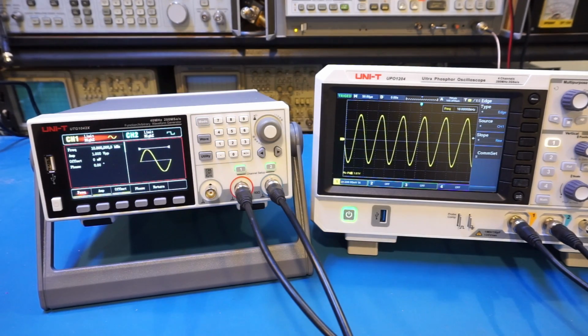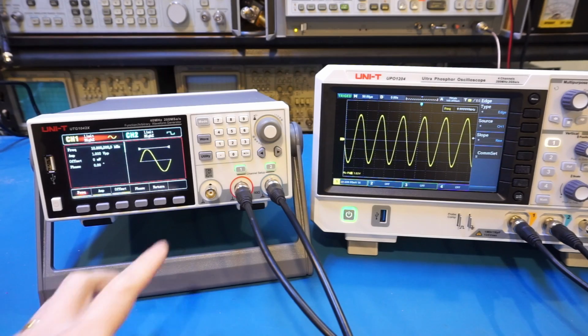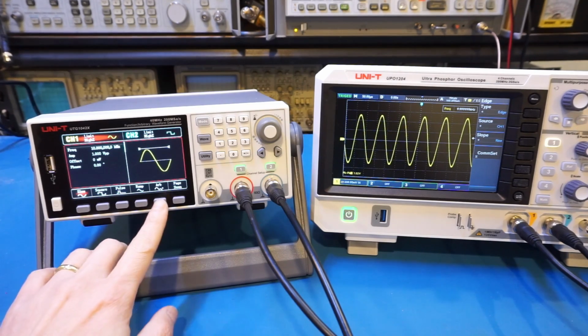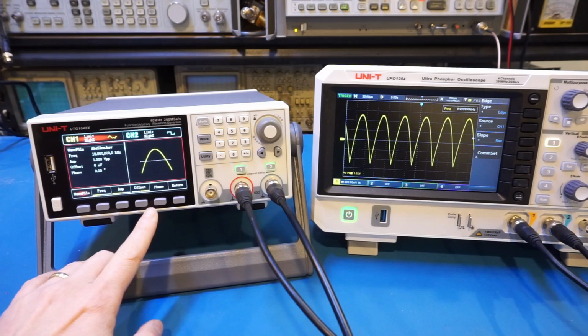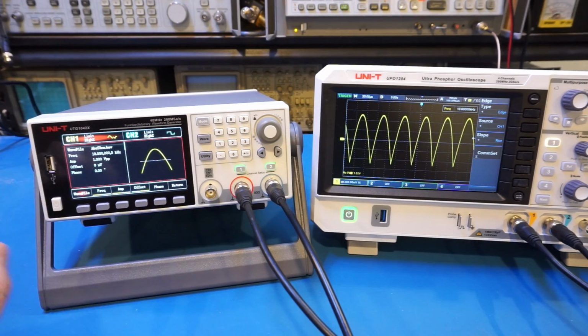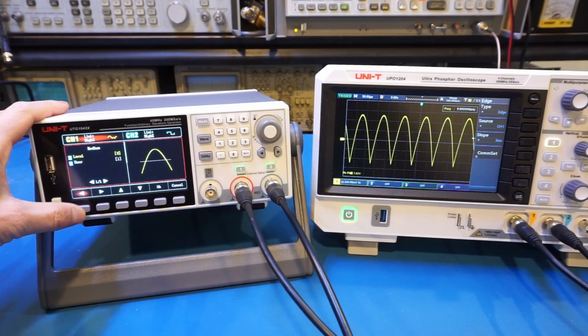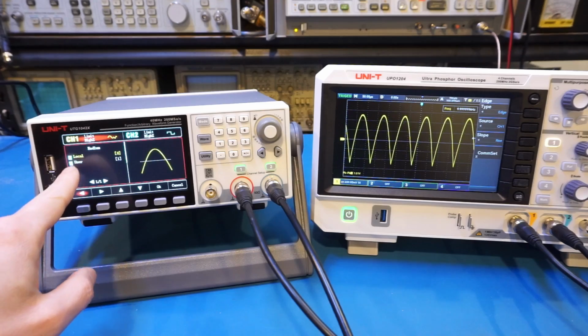Next, let's take a look at some of the built-in arbitrary waveforms, as after all, that is one of the key selling points of the 1042X. So let's go back here. Let's go to arbitrary waveform. Now, the way it is actually structured is a little bit confusing here. And you can see here, to select the actual arbitrary waveform, you have to go to the wave file. And currently we have local and user.